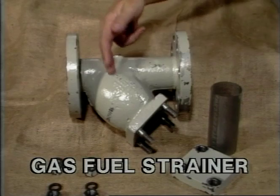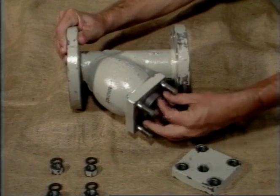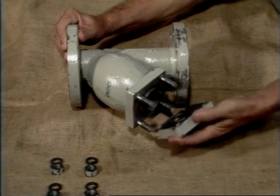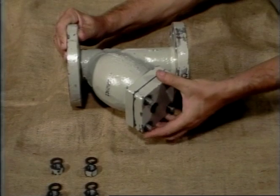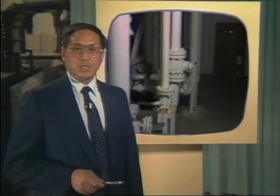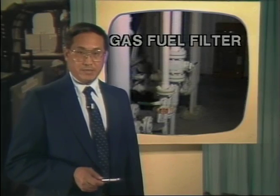Initial filtering of gas fuel takes place at the Y-shaped cast steel strainer with a 40-mesh cylindrical screen. A clean-out plug located on the lower branch can be removed for cleaning. An optional gas fuel filter may be installed off-skid.